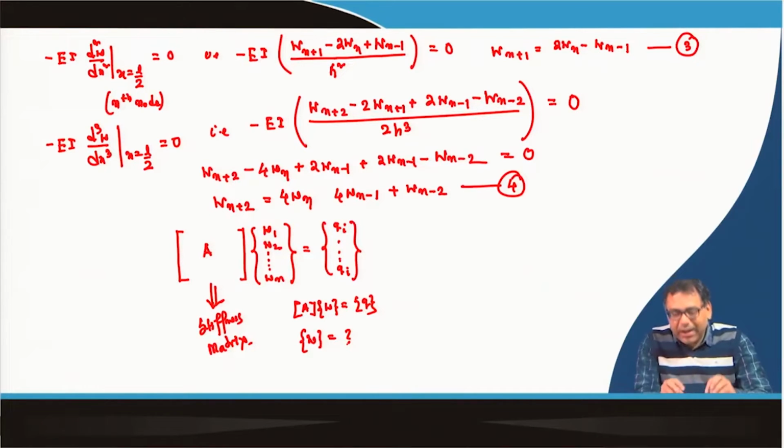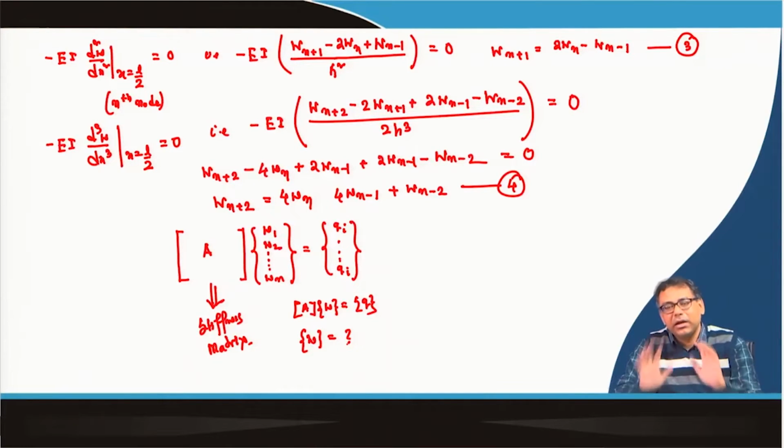Once you apply these equations on n number of nodes, you will get n equations, and now all the equations can be replaced with real node deformations. Express them in matrix form, with the deflection vector and the load vector.